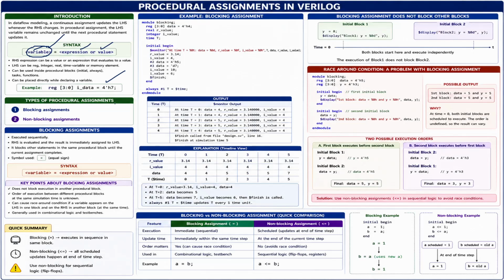We use different types of procedural assignments: blocking assignments and non-blocking assignments. Blocking statements are used in combinational circuits, that means the data flow model. And for sequential circuits we use non-blocking statements. See, how do we represent blocking statements? With the equality symbol, just equal. For example, variable a is assigned some bitwise operation like x and y, so this variable stores the operation x and y.